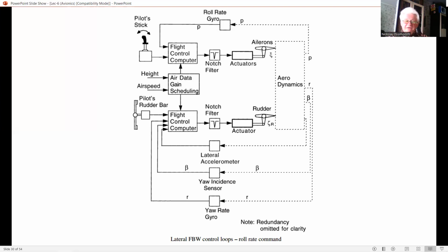Hence, if the pilot increases his gain in an attempt to get tighter control and overcome a lag in the aircraft response, the consequence can be that the aircraft becomes more out of control. The pilot gets out of phase, and the harder the pilot works to control the aircraft, the worse the situation becomes, and the PIOs result.